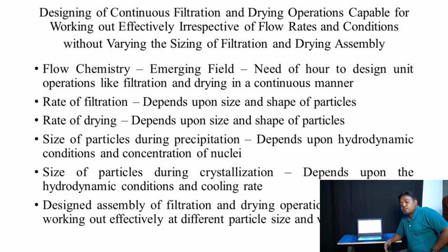As the size of the particle increases, the voidage between the particles increases, therefore cake resistance decreases and the filtration rate increases. Similarly, as the particle size increases, the voidage increases, and therefore the moisture in the bulk of the solid gets removed easily, so the drying rate also increases.